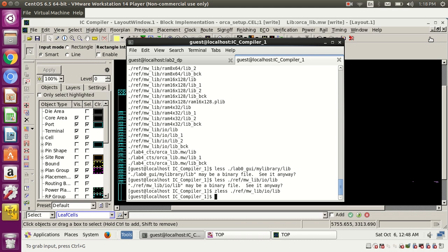So now see what we want. We want a clock. We want to give the clock to the flop. Based on this diagram, what is our time period? 10. How is it 10? Because one complete cycle is done in 10 seconds. So based on this 10 units, whether 10 ns or 10 ps, we'll do hold check and setup check for all the flops.